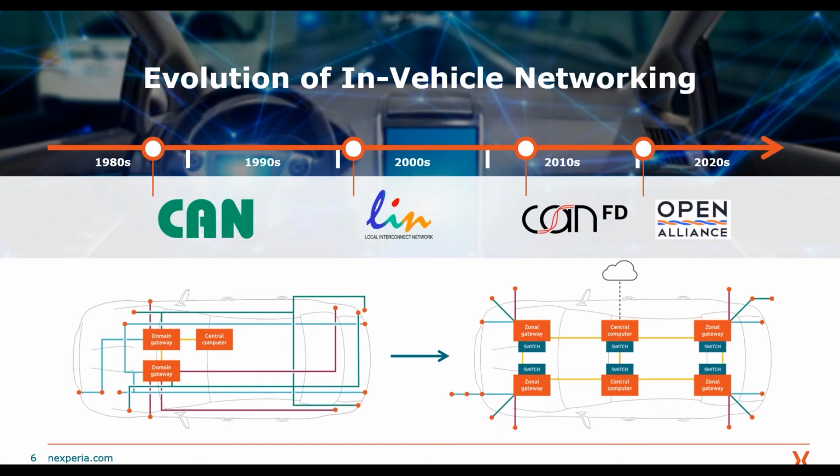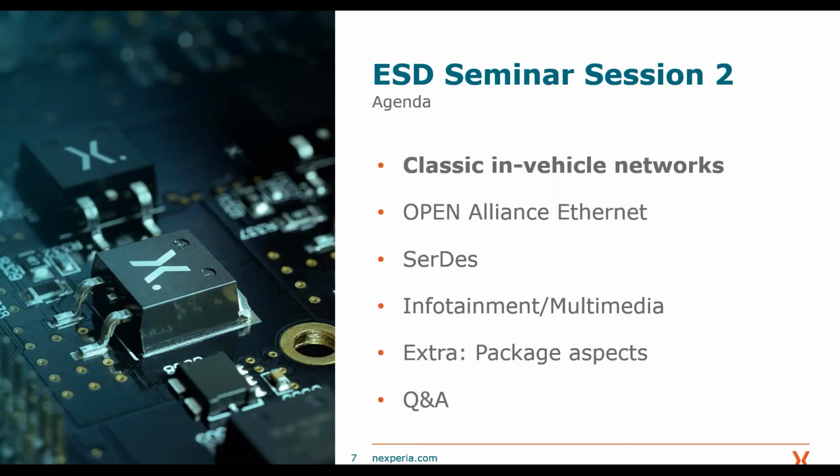And therefore, we need new protocols, let's say new streets, for how we transfer this data. We now come from this hierarchical network, where we have an end-to-end connection, to the, let's say, IP-based car with Automotive Ethernet, where we can realize all the software demands we see happening in the car. So we will start with the low-speed device protocols, starting with 20 kilobits per second, and now Andreas will talk about the LIN bus.